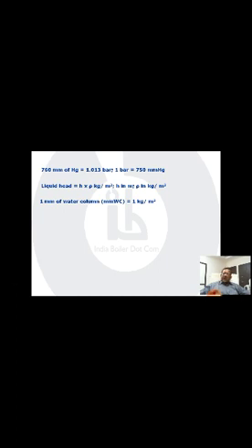So, you see, when you say mmWc, we are talking about kg per meter square, both are same. Please remember this is going to be very useful for your examination. If you see, kg per meter square, it is either kg per meter square you can write, or 10 raised to minus 4 kg per centimeter square, or it is 1 mmWc. And similarly, 1 kg per centimeter square will be 10 raised to 4 mmWc. And that's why, in the field also, we take 10 meter of water column as 1 kg per centimeter square.